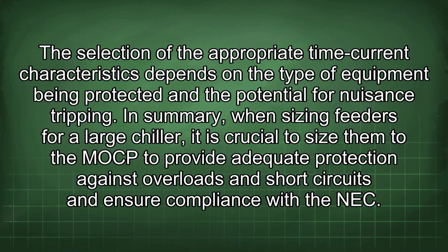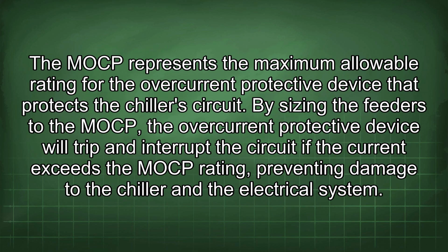In summary, when sizing feeders for a large chiller, it is crucial to size them to the MOCP to provide adequate protection against overloads and short circuits and ensure compliance with the NEC. The MOCP represents the maximum allowable rating for the overcurrent protective device that protects the chiller circuit. By sizing the feeders to the MOCP, the overcurrent protective device will trip and interrupt the circuit if the current exceeds the MOCP rating, preventing damage to the chiller and the electrical system.